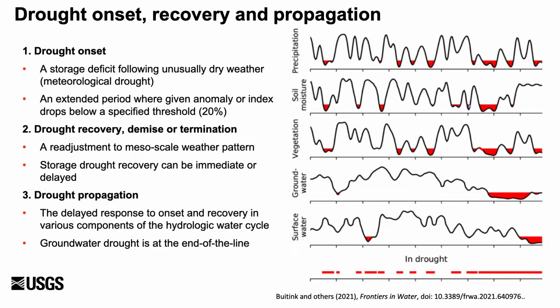Drought metrics, like the Standardized Precipitation Index for rainfall and the Palmer Drought Severity Index for soil moisture, are used to characterize drought severity as the product of its duration and magnitude. These indicators reflect physical drought impacts in various sectors that cannot easily be weighted or aggregated through some sort of direct measure. As such, indices are critical for drought mitigation and operational water management.